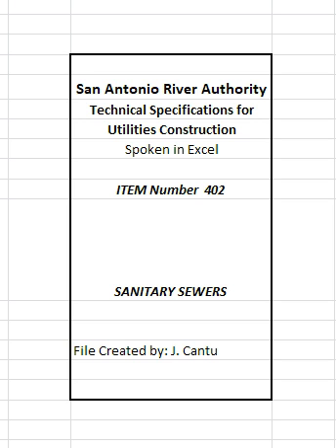The sizing criteria for a sand interceptor shall be based on the required g.p.m. x 12-minute retention times to obtain the tank size in gallons capacity. Automatic car washes with high-pressure sprays and or brushes install a 50 g.p.m. interceptor minimum. For a 4-bay vehicle wash, the size of the interceptor shall increase 10 g.p.m.